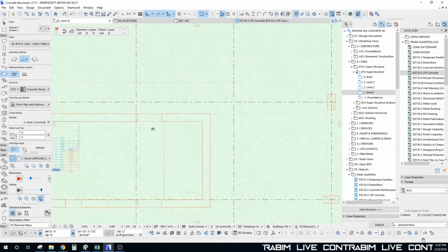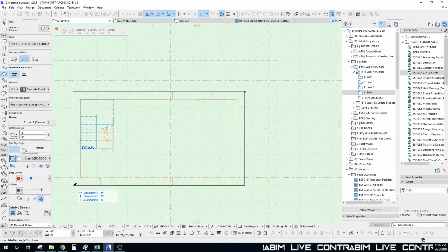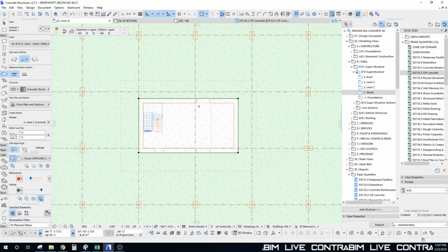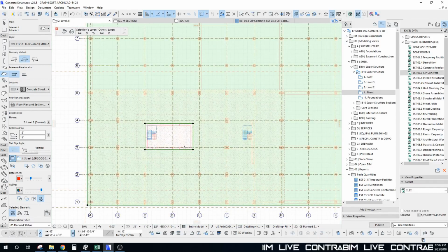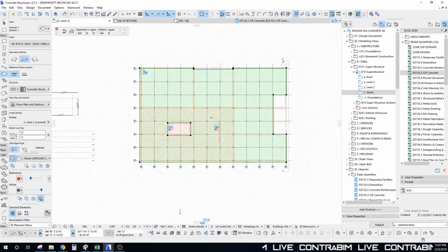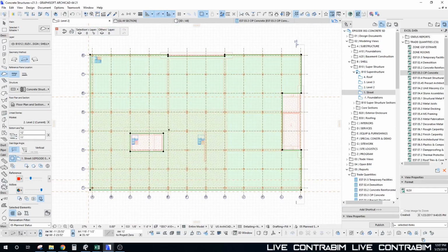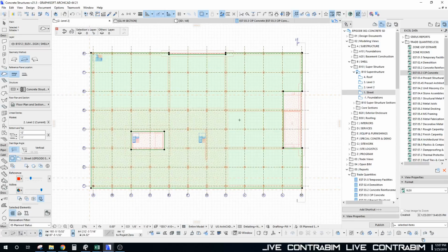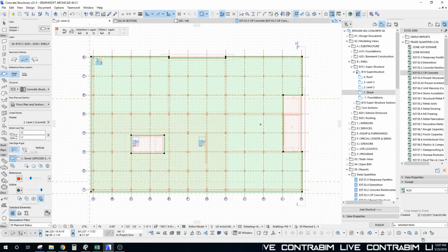And okay, the other thing is I need to trim out this component. Because the shear walls are going to go up first, you're going to be pouring those one level after another, and you're not going to have your slab intersecting those like you would other elements such as columns or beams. And so we'll just leave that as is like that.